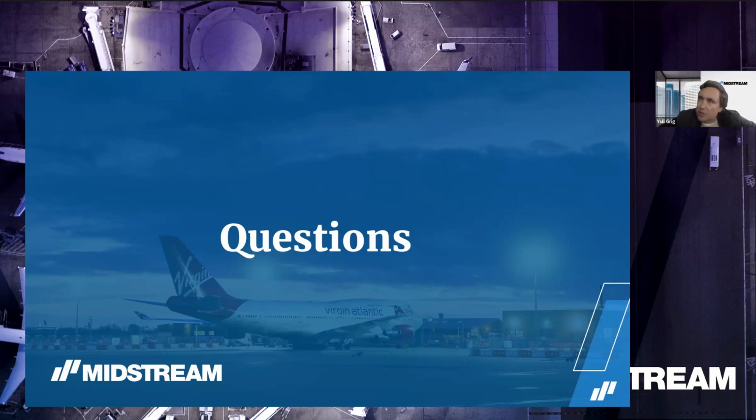So Paolo, let me ask a question then, because what we've sometimes seen is certain airports have said, well, we want to ensure that there's no depreciation on our apron from the floodlighting. So we would like to have a starting point of 40 lux or 30 lux, or indeed somebody has asked here, what if we recommend an average of 60 lux? In that instance, are they already anticipating the maintenance factor by setting a higher lux level, and therefore they can set the maintenance factor to 1?